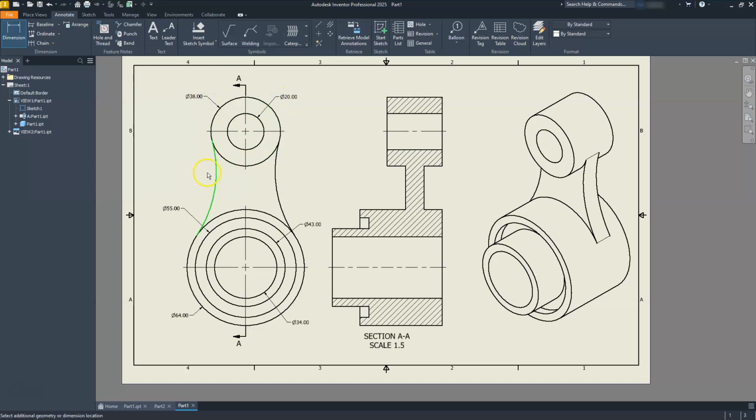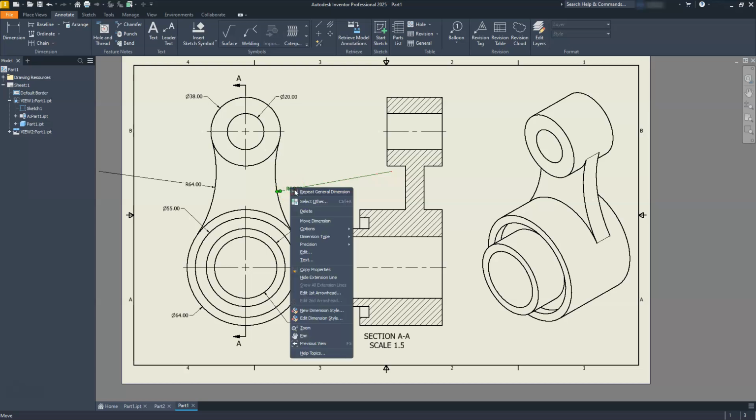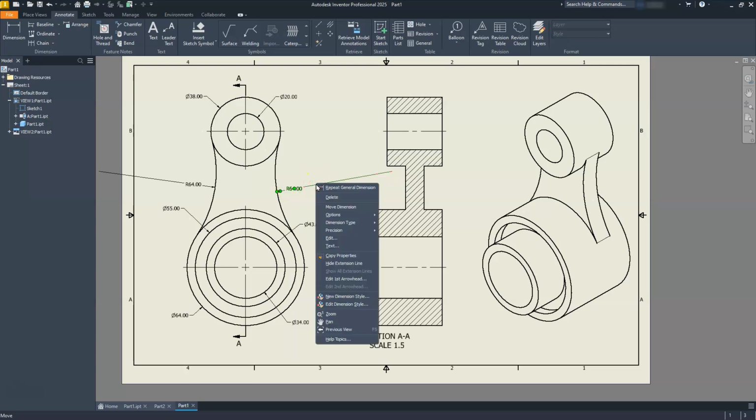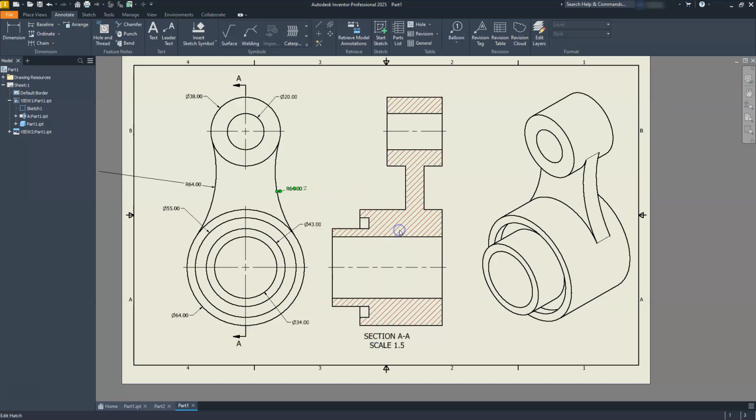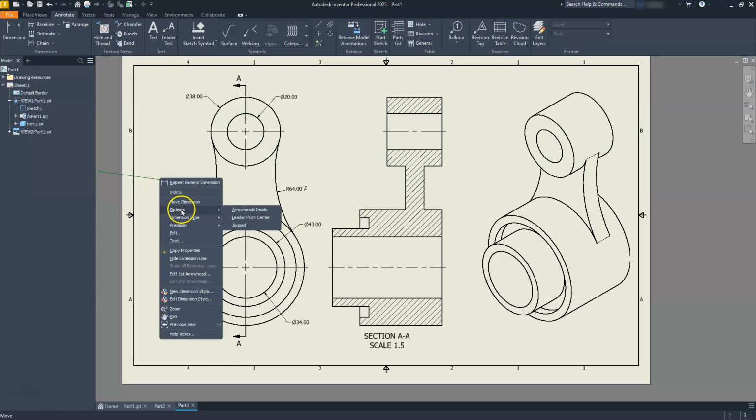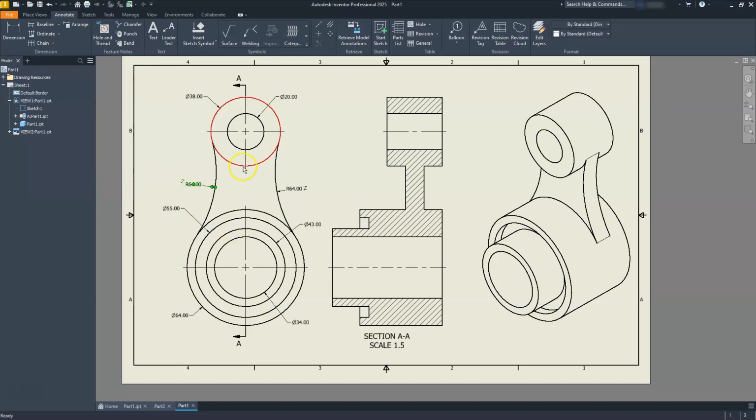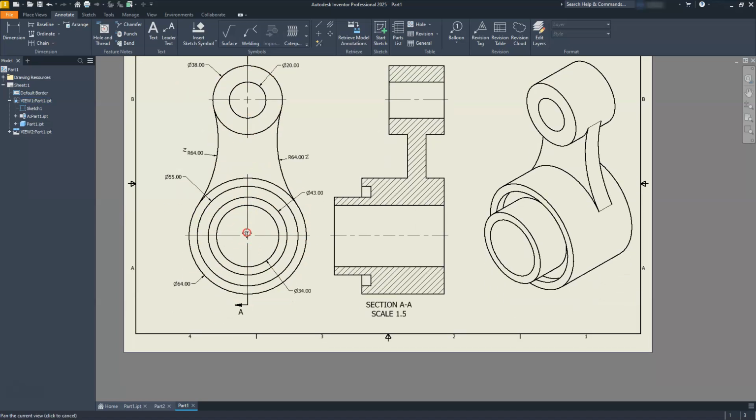Let's go ahead and knock out these radius dimensions. I accidentally found the center point on that one. Let's go ahead and click here. And now these are ones where I may have to do a jog on them. Well, actually, I think I will have to jog them. And let's see, dimension type. I gotta go in the options and then go to jog. And then there's that one. I'll select this one, go underneath options, go find jogged, and I'll have that one. Okay, so I have those 2 done. Now I have all of my dimensions done on here.